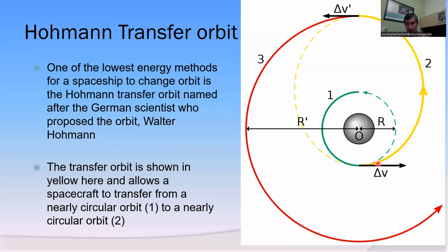Okay, let's say that now this is Earth and this is the sun, and we want to get to Mars. This transfer is actually done twice. And the problem with this is when we get to ion engines, which have a very low thrust, they actually lose some efficiency, because the low thrust means that, unlike a chemical rocket where we can produce a large amount of thrust all at once, we're not producing this delta V at the optimized point in time.